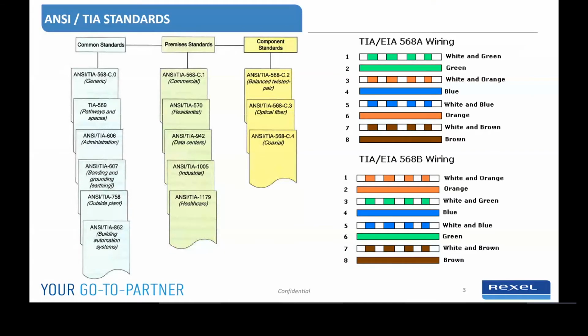This would be important across the network, because could you imagine if every device on your network had a different wiring format? Every device was wired a little bit differently. If I went from a Yokogawa VFD to a Rockwell VFD, and they had different wiring, I'd have to re-terminate that wire, re-plug it in. If I ever changed out a switch on the network, I would potentially have to change out all that wiring, how it went into the switch, if they all had different wiring standards.